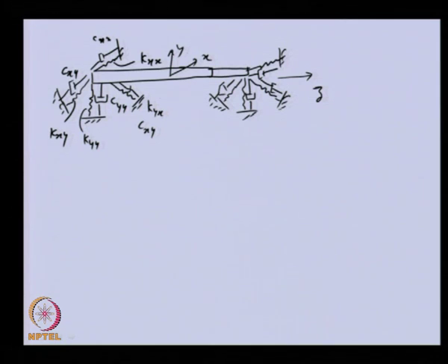That is why I have changed the subscript of the coefficients to x and y. So, this rotor which is mounted on the two bearings is identical to the previous analysis. The only thing is now we have so many spring and damper coefficients attached to it.